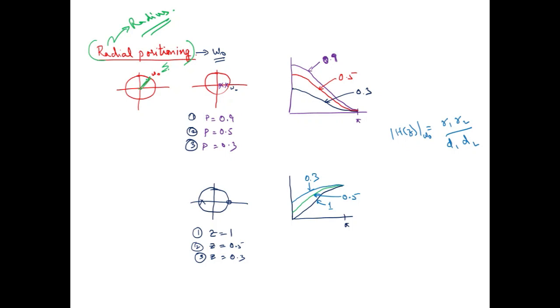Say, for example, if I place a pole over here at a 45-degree angle, I can change the radius, and by changing the radius I can play with the amplitude at the resonant frequency. I can vary the amplitude at the resonant frequency, and that effect will be maximized by that pole over there.